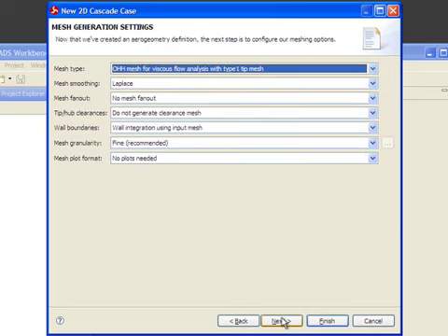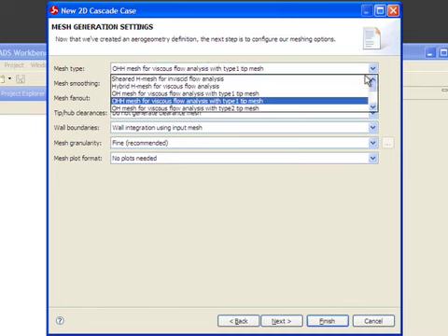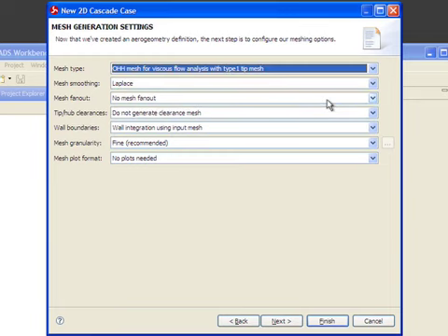Now that we've completed the definition of the information needed for the aerogeometry file, we'll move on to mesh settings. The first thing to do is to specify the mesh type. Though we offer a number of different mesh topologies from which to choose, we strongly recommend that you stick with OHH mesh for 2D analysis. OHH mesh provides more uniform mesh distribution at the leading and trailing edges, which leads to better insight into the flow physics at both locations versus OH mesh.